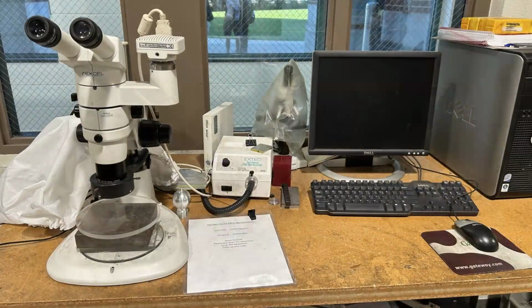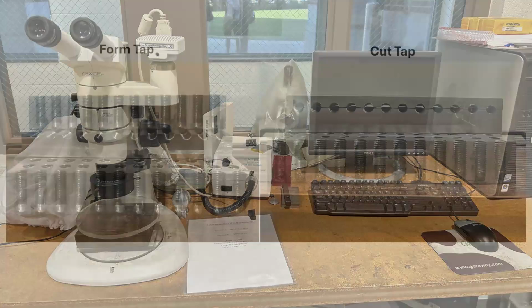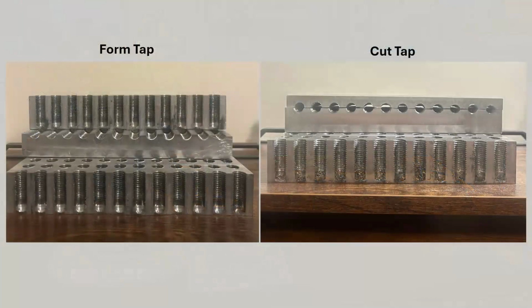After machining, we took the used tap to this microscope and took up-close pictures to identify any built-up edge or chipping that could occur on the tool. Once completed with the blocks, we cut open the tapped holes to analyze the quality of the threads on the inside.